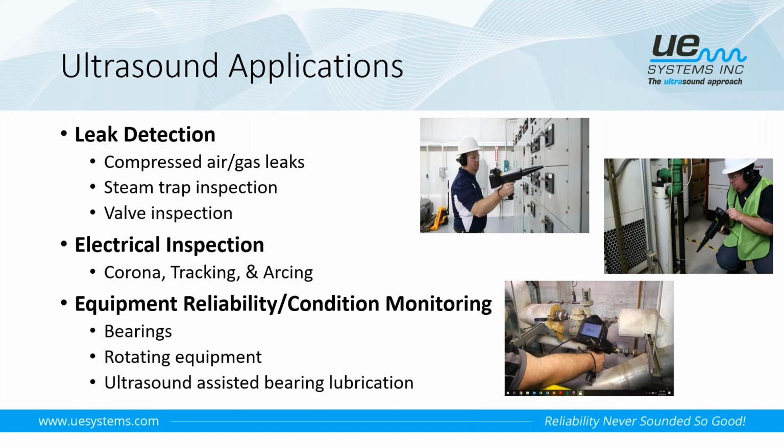Another airborne application, leading into talking about the versatility of ultrasound, is that any of those four instruments that I showed previously can be used for all these applications. So we're not just limited to leak detection, but the same attachment that we would use for airborne leak detection would be the same attachment that we would use for airborne electrical inspection. So you see in the photo here, we're scanning this MCC or the switchgear here, and we're listening for faults like corona, tracking, and arcing. It's an airborne application where we're going to hear those sounds through any of these openings.